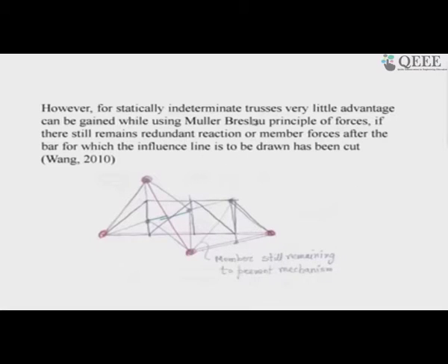For statically indeterminate trusses, I should say it will not be that easy, because in statically indeterminate structures there won't be rigid body movements like this. It has to bend for a beam, and for trusses there will be other redundant members present which will be further loaded. The load will increase or change, but it will not be relieved to immediately show you the rigid body movements of the parts like this.